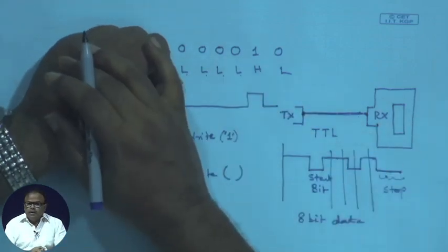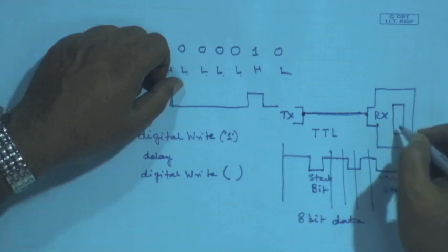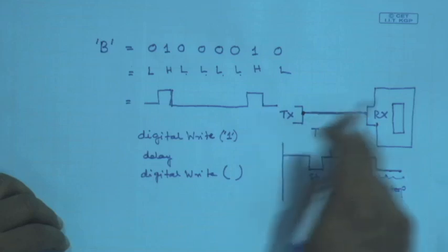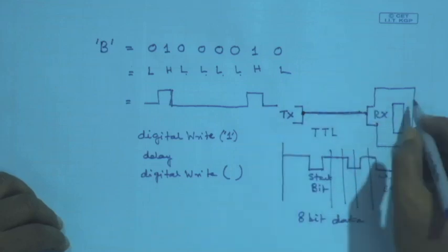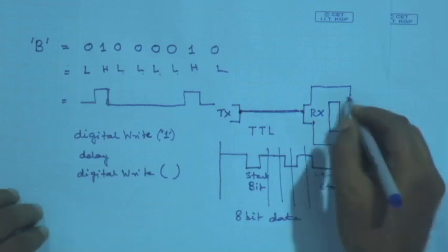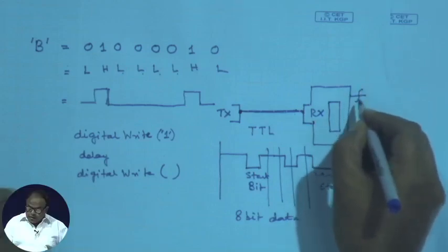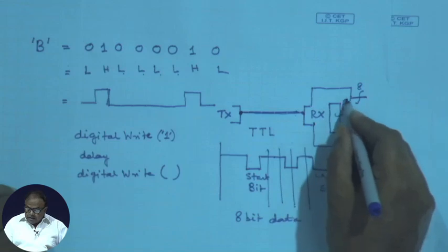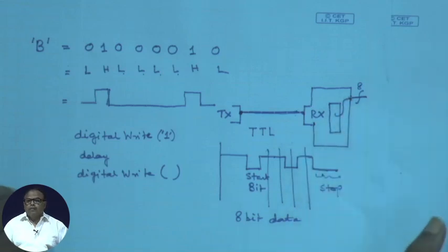You are loading it in a register, and that is very simple, that you can do using a shift register, or even in a memory location you can do that easily, right. So then it becomes parallel data, and if you have some parallel out ports, say 8 bits, 8 lines coming out of this, then this entire data can be transferred in a parallel form.